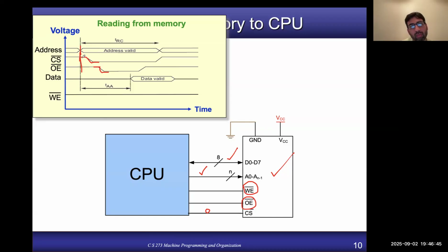So if you, for example, set the chip select signal or output enable signal at the same time point, but the internal circuitry of the memory chip has not yet sensed the new address which you have placed, because it takes some time for it, then maybe it will give you the data on the output which corresponds to the older address, for example this address. So it takes some time for the address signals to be stabilized in the internal circuitry of the memory chip.